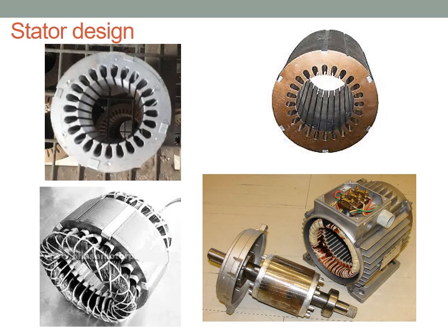So now these are the pictures of the stator core. The stator is made up of thin laminated stampings, with a thickness of around 0.3 to 0.5 mm. These stampings are very thin and varnish coated, and they are stacked together throughout the length, this is the length. To reduce hysteresis losses, they are made of thin laminations.